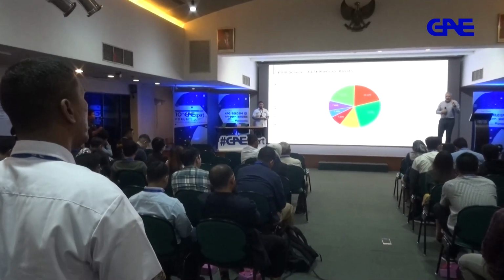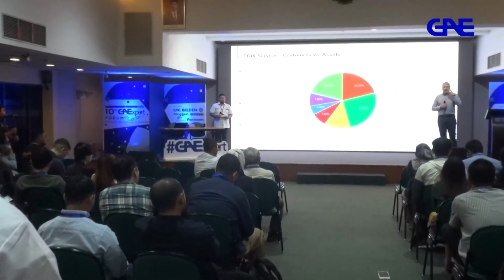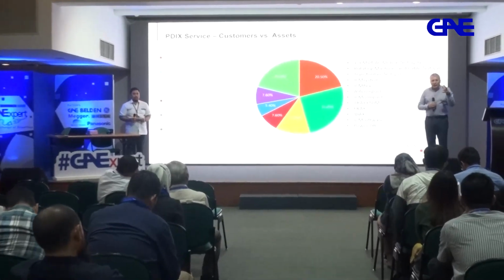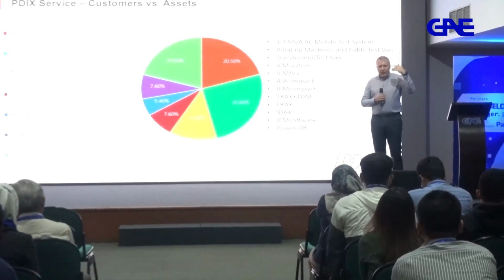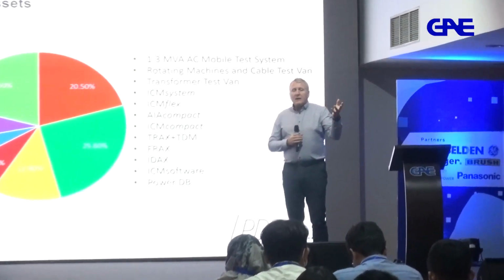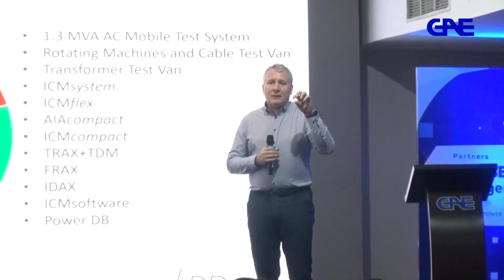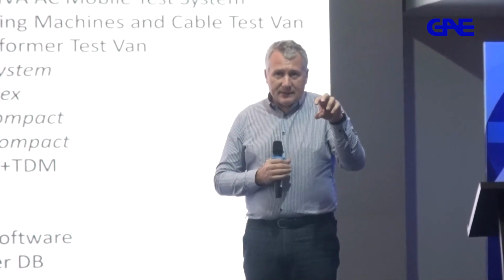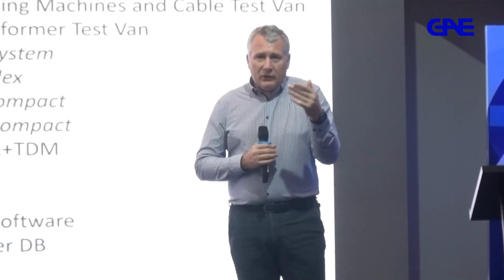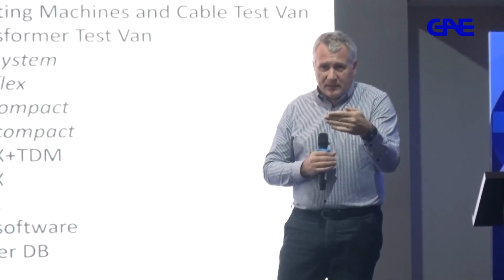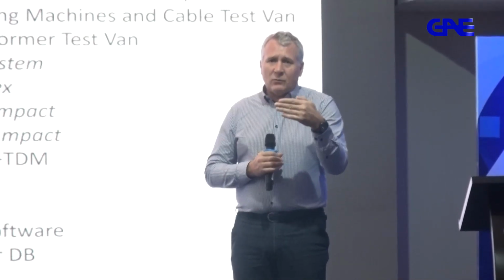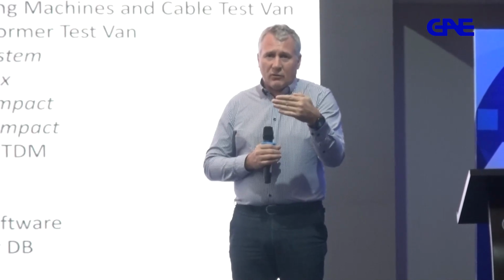The only problem now is, do we see this corona covering, in other words, if we have very powerful corona, do we see that covering the real partial discharge problem inside of that asset? And this is the place where you need to have a specific measurement done. You need to understand the conditions, and then you need to understand what you can do to suppress that corona.